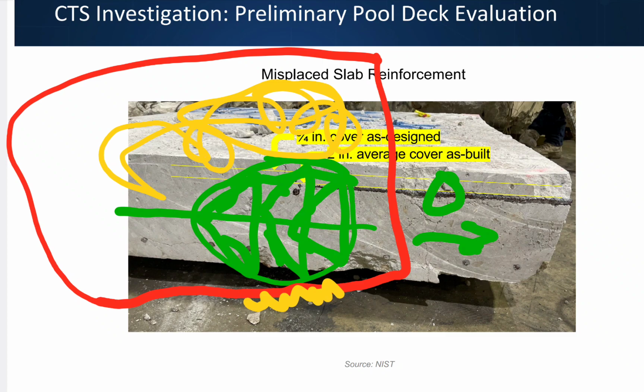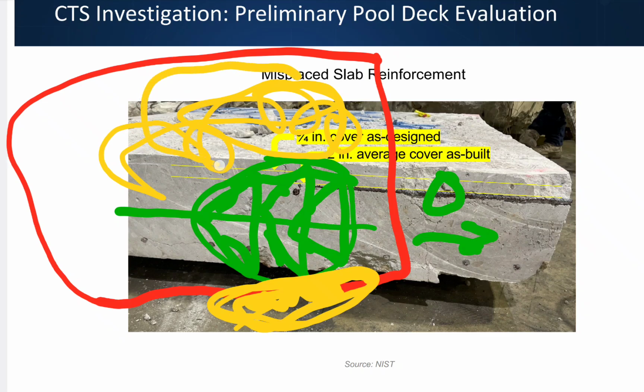It's just cover to protect it from rotting and everything else. No, that spalling indicates that that's part of that pressure cone that's failing. Even if you can't find rust as part of the issue, part of that pressure cone that's failing, this blasting out away from the steel pressure cone, is because there's not enough stirrup concrete, if you will.